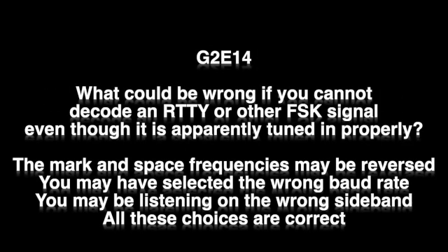G2E14. What could be wrong if you cannot decode an RTTY or other FSK signal even though it is apparently tuned in properly? The mark and space frequencies may be reversed. You may have selected the wrong baud rate. You may be listening on the wrong sideband. All these choices are correct.